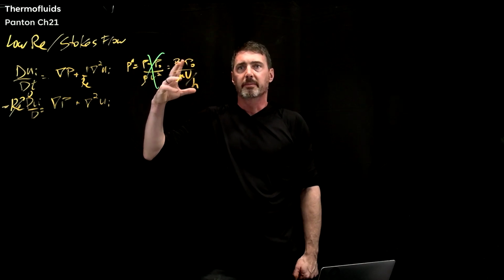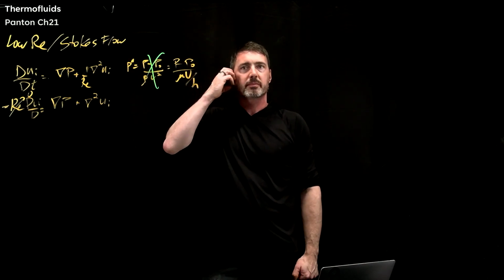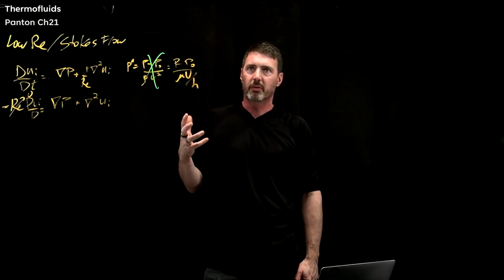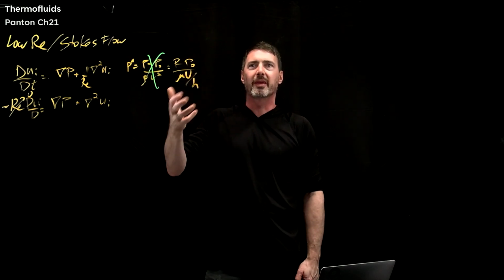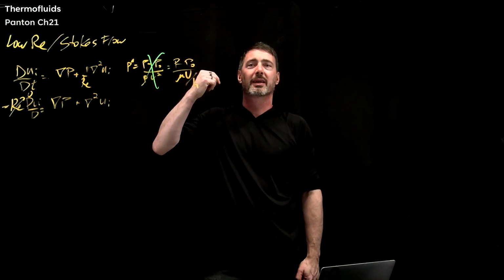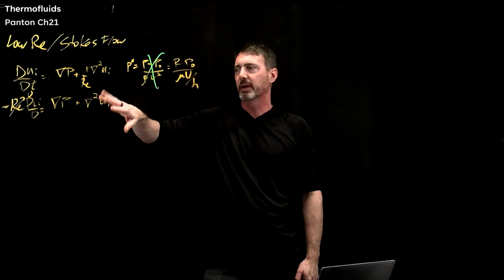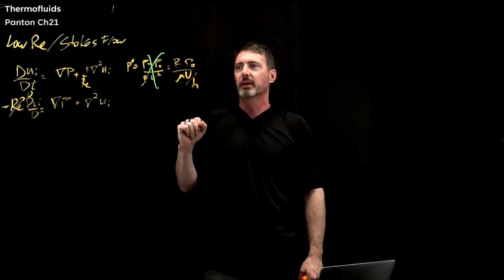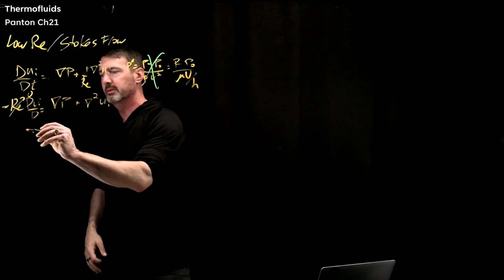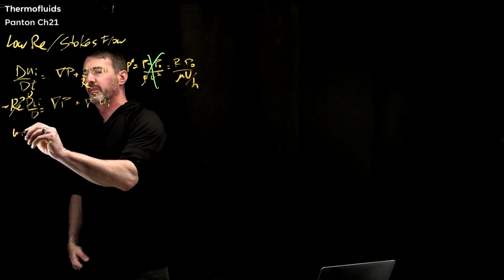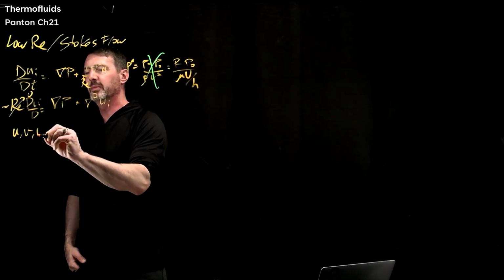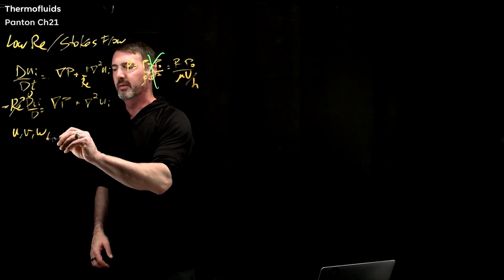Now, one of the ways to look at pressure, which comes up if you take a computational fluids course, is this way: you have conservation of mass, and then you have conservation of momentum. In the incompressible world, where rho is just a constant, what do you have? You have 4 variables: u, v, w, the x, y, z velocities, and then pressure.